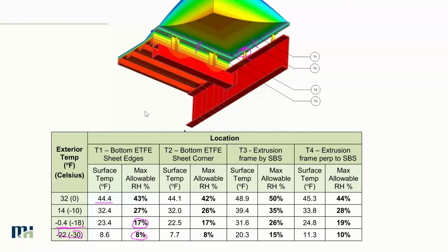So what can you do in those situations? I think in this particular case, the decision had to be made whether or not you put in supplemental heating systems, whether it's baseboard heaters or some sort of unit heating system, that when this occurs, they can turn on and keep this whole area warm, so that you don't risk condensation falling down onto the stands.